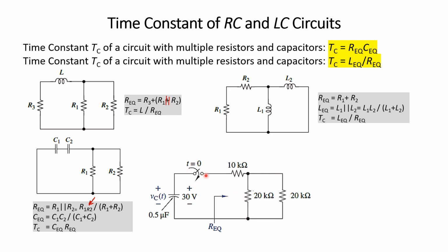We will use this, you can say it is a circuit element, a switch, and due to this arrow it means that normally the switch is open, and at t equal to 0 we close it. t equal to 0 is the time instant when we start the analysis of our circuit, and at this instant when we close the switch we determine the initial voltage across the capacitor or initial current flowing through an inductor due to stored energy in these energy storing elements.